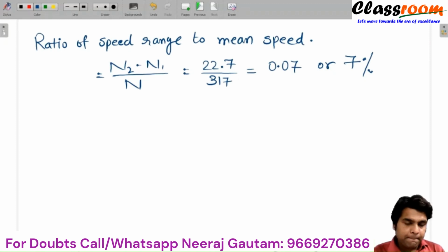So in this way, you can solve problems based on the Hartung governors by drawing the configuration diagram. In problems of governors, the configuration diagrams are very important. You have to draw the configuration diagram for minimum speed, for the maximum speed, and for the mean speed, and you can solve any type of problem using the geometry as well as the basic fundamental equilibrium equation.